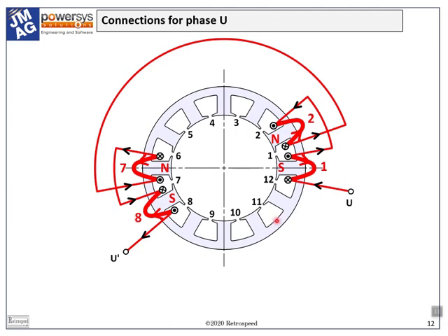You can see that we've used a short connection between two nearby coils, leaving only one long jumper or long interconnector between the two groups of coils. Of course, we will have to bring these terminals closer together for the terminal box, so we will have another long connector in this region.